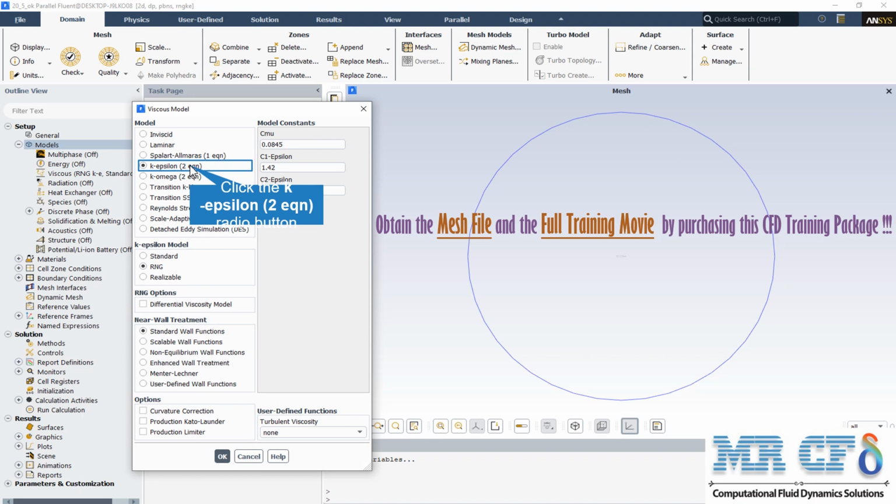Effective use of this feature does, however, depend on the appropriate treatment of the near wall region. These features make the RNG K-epsilon model more accurate and reliable for a wider class of flows than the standard K-epsilon model.